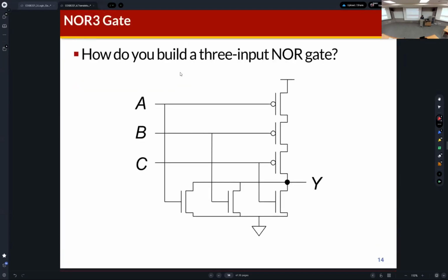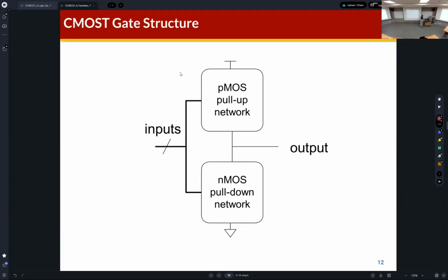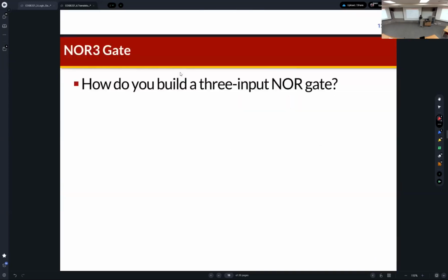And that's also why, in a CMOS transistor circuit, the PMOS is only connected to the VDD. It is because PMOS can pass 1 clearly, but PMOS cannot pass a 0 signal clearly. That's why the PMOS transistor is only connected to the VDD. Then the NMOS transistor, inversely, is connected to ground.